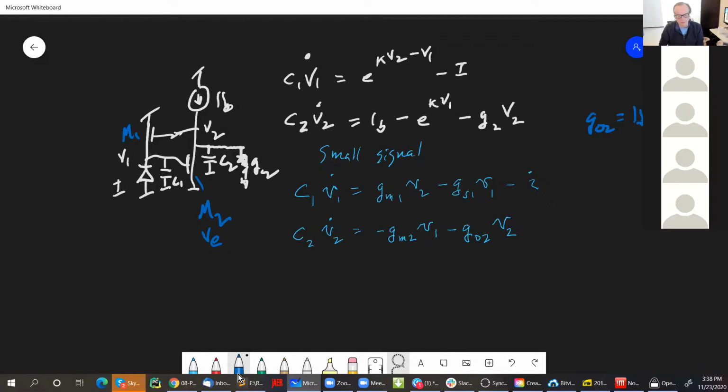That's clear, right? What about GM2? GM2 is the subthreshold transconductance operating at a current of IB. So what's that? Come on, somebody tell me. You guys must know this. Kappa IB over UT. Yeah, thank you. Kappa IB over UT, and so on. We definitely expect you to be able to do these kinds of calculations, okay?